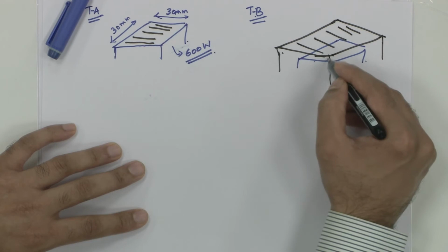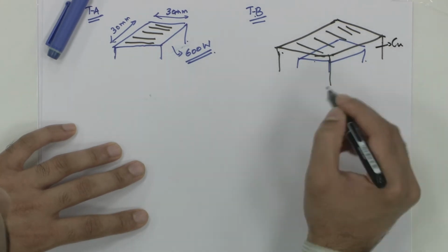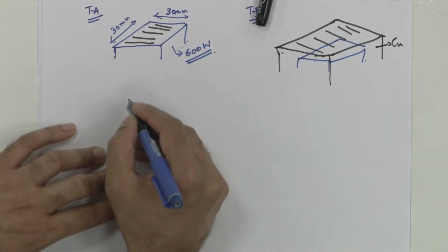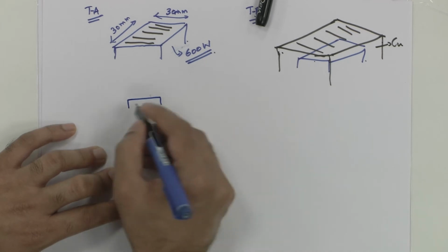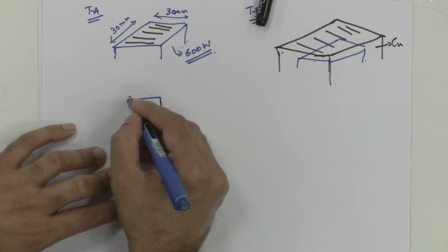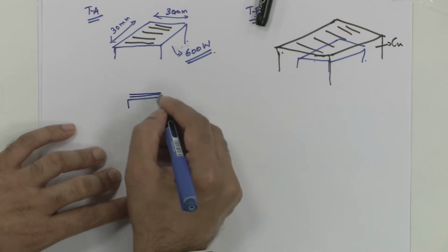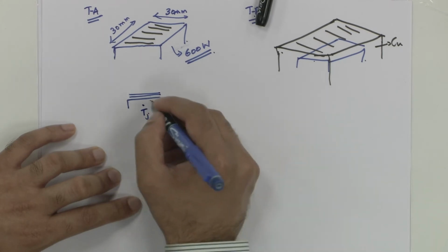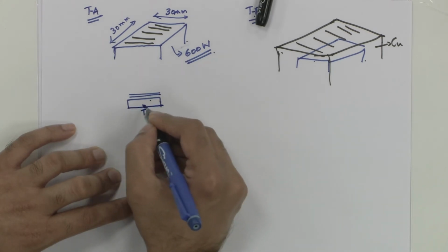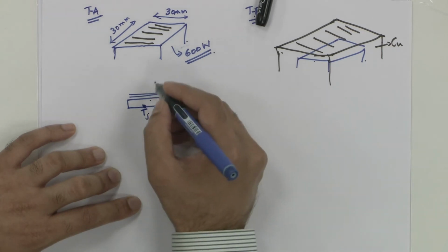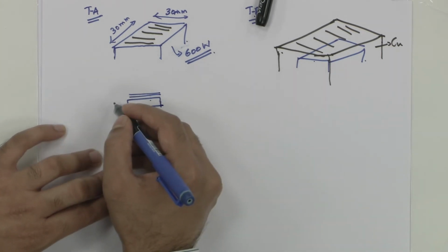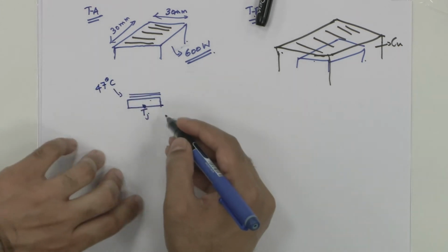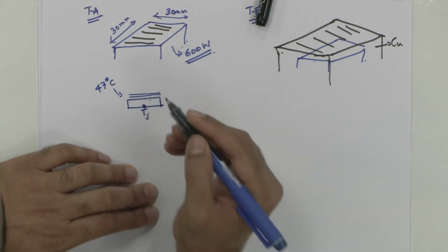So, this heat spreader is made of copper, and if we draw a 2D cross section of this, now you have a silicon and there are some microchannels laid on this. So, this is the junction temperature, T junction, and the liquid water comes in at some 47 degrees Celsius to recover waste heat from this, assuming 100% fin efficiency.